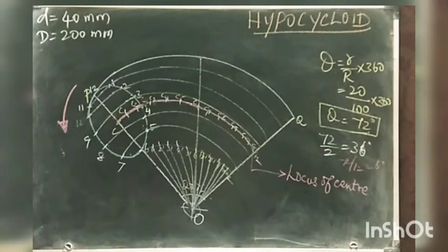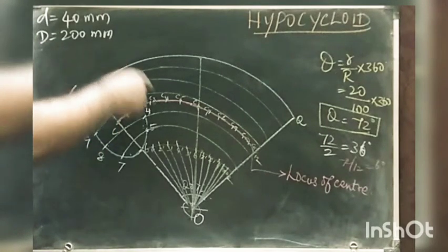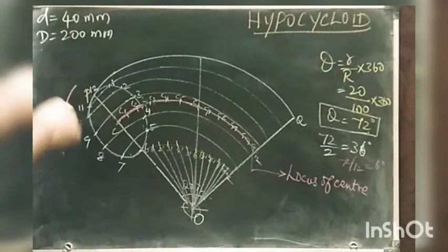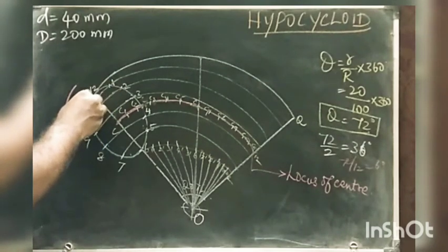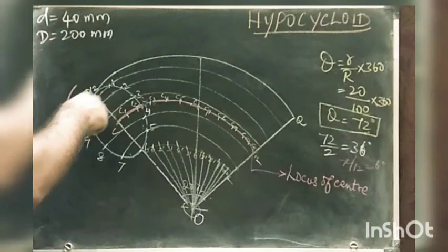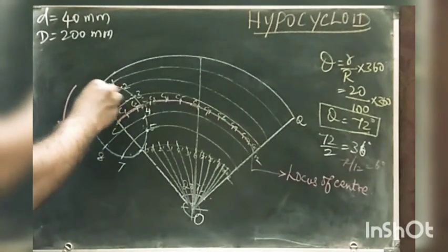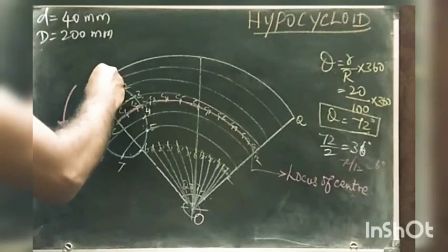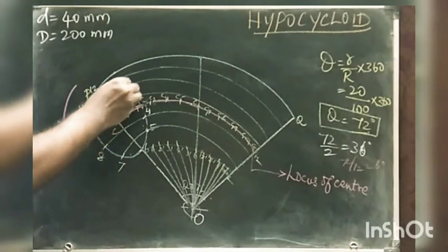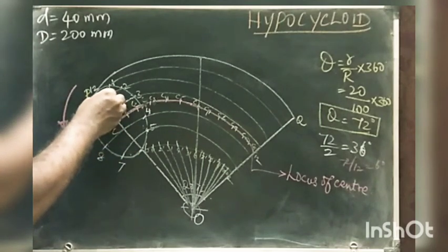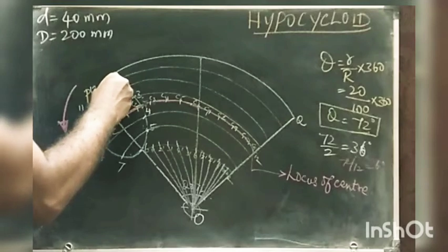Now next step, what I am going to do is place your compass at the point C1, take the radius of the rolling circle and cut an arc. Where we need to cut an arc, that's very important. See here the first line where it is, first arc, yeah, it's here at the top, right? It's entirely different. So cut an arc in such a manner, you may get it like in this manner. Okay, and similarly C2, place your compass at the point C2 and cut an arc.